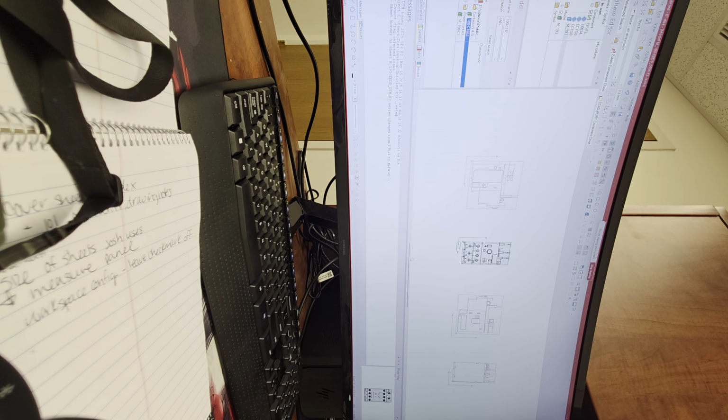Now, just to show you the principles behind these things, in your model device structure on the left side, expand that little model name. So not the library, but your little temporary editor up on top. Under model, expand that so you can see the full contents of it, okay? Whenever you import a step file, like in this case, there was a step file, there was a model for this thing. When the step file is imported, the import process creates these side views, bottom views, top views, etc. that you see here grayed out.